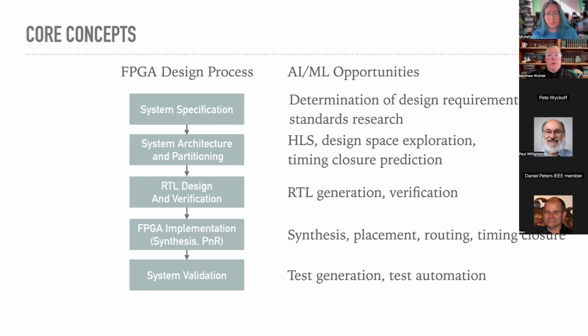there's, especially like placement is so key to having a good timing closure. If you don't have good placement, you'll end up with long routes and having difficulty closing timing. So placement algorithms are one of the core things of EDA tools, getting good placements. And there's work now with AI agents to help assist the placement process. Because right now they're algorithms, but sometimes as human beings, we can look and say, those placements are really bad.